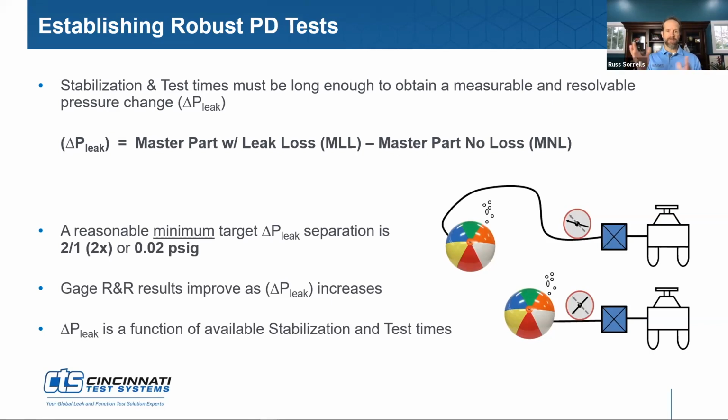And that's because of the tearing method that we're using. We're using a part to calibrate to, and that establishes zero for all of the other parts. And so if one has a negative flow rate associated with it, that means that it had less pressure loss than the part we calibrated to. Negative leaks is a common conversation that we're having with our customers, and sometimes a tough thing to wrap our mind around. Yep, absolutely.